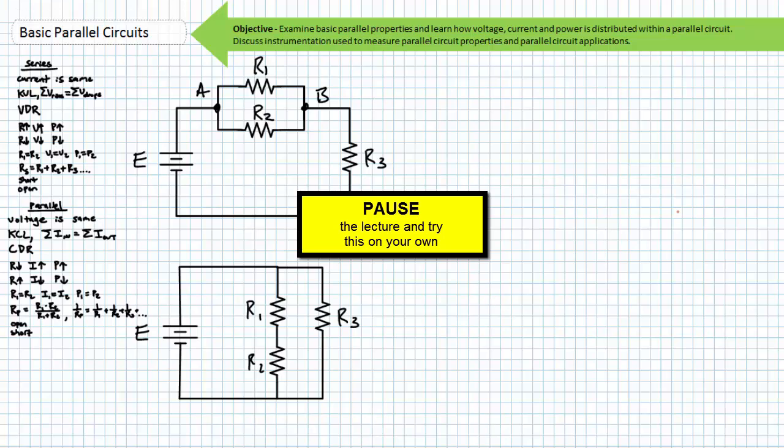This may seem challenging at first, because we've only had the briefest introduction to some of these properties, but realize there are no numbers in this problem. All I'm asking you to do is, again, visualize this circuit at the nodal level and from the perspective of flowing current. Current through elements hooked in series is the same. Voltage across elements hooked in parallel is the same. For every rise there is a drop, and what goes in must come out.